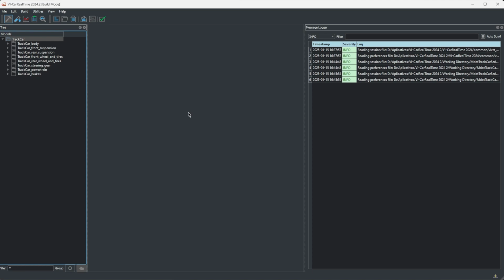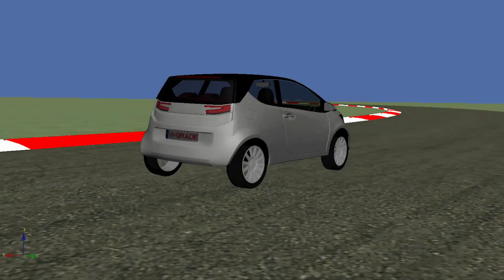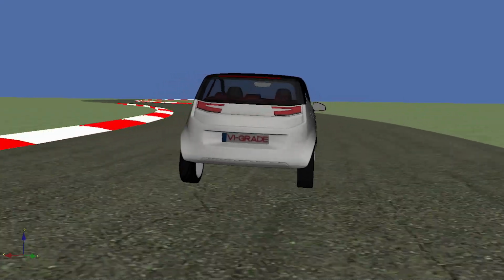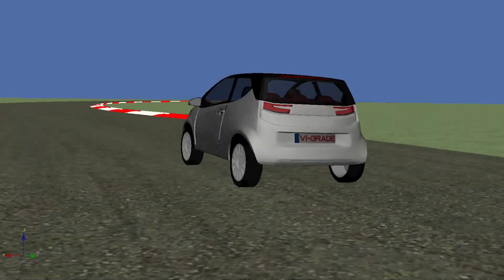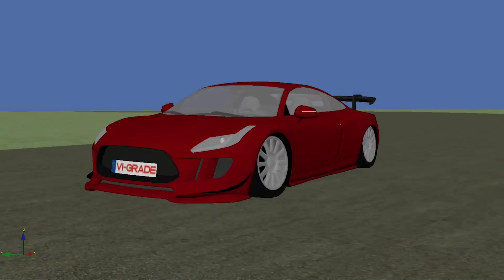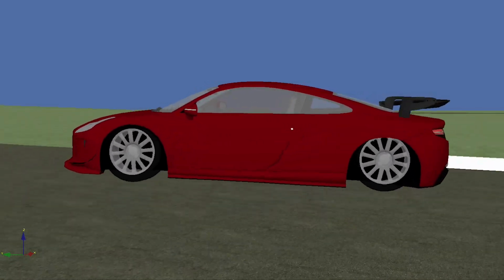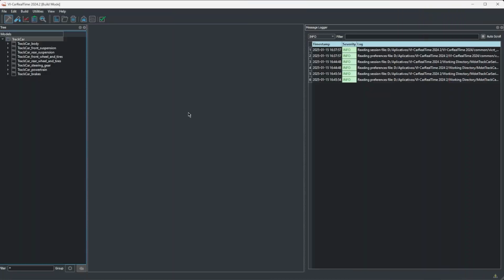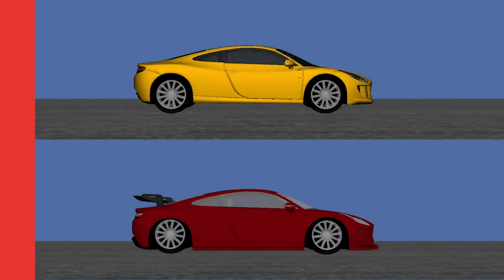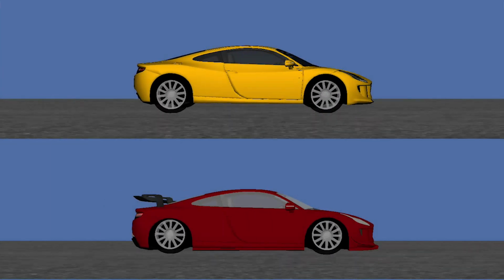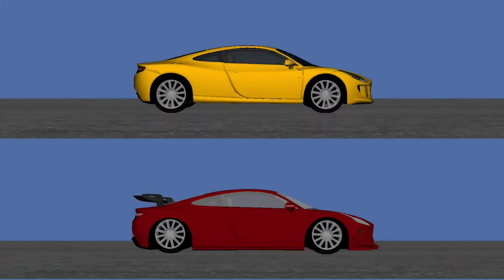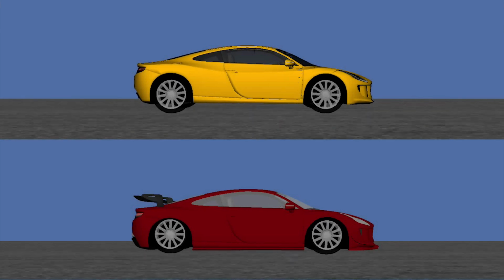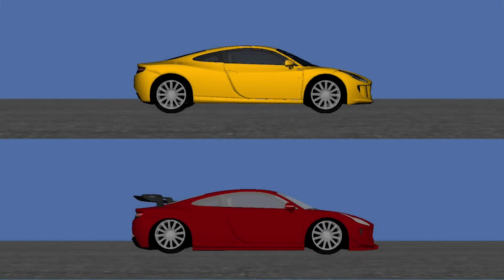Kinematics can be designed for different goals, like helping a street car provide efficient tire wear for long periods of travel at modest speeds, and also helping track cars perform their best by providing optimal tire positioning in high-performance applications. Even though our initial kinematics are based on those of a sports car, they can be further optimized, and the changes we made to ride height when implementing the aero package can have influenced them negatively.